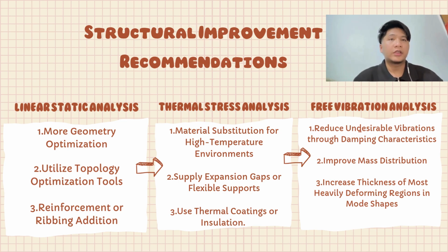For structural improvement recommendation, for linear static analysis, we need to optimize more on geometry. Secondly, we need to utilize topology optimization tool. And thirdly, reinforcement or ribbing addition. For thermal stress analysis, firstly, material substitution for high temperature environment. Secondly, supply expansion gap or flexible support. And thirdly, use thermal coating or insulation.